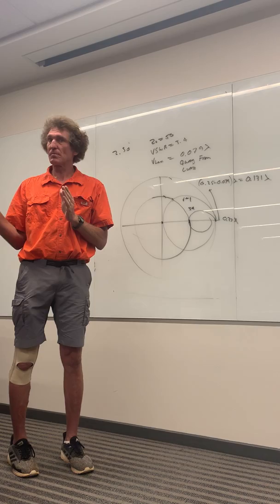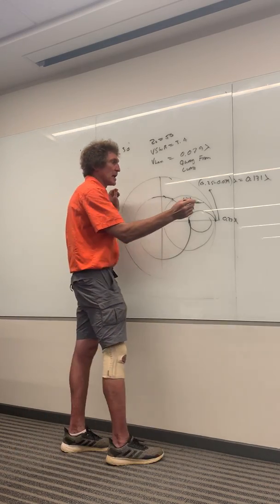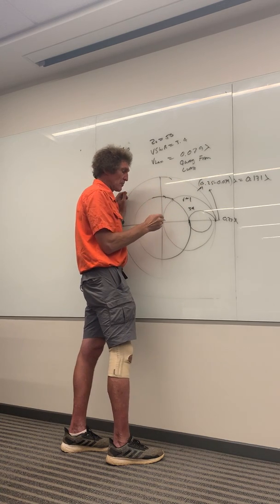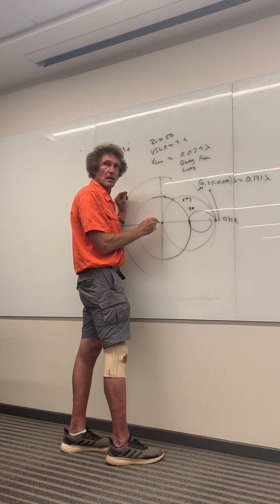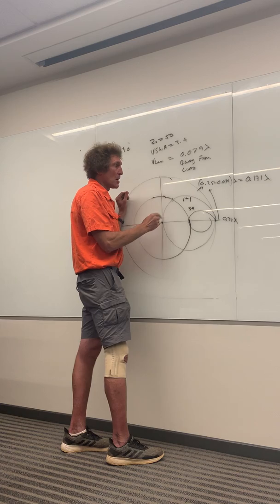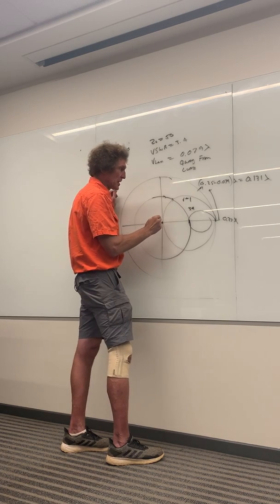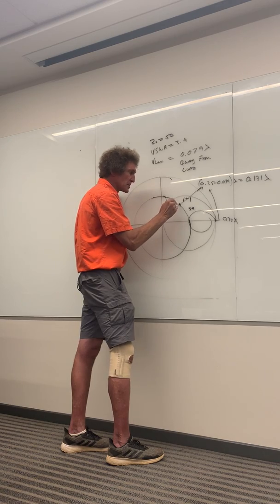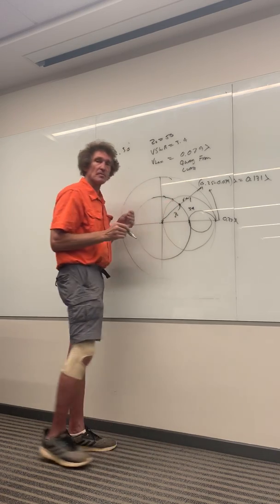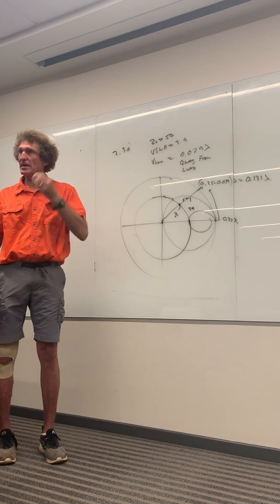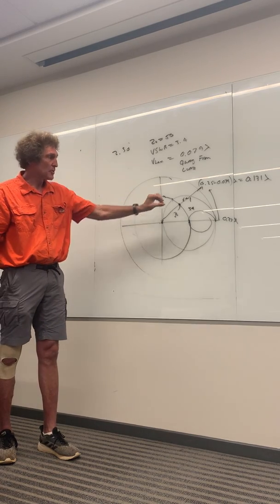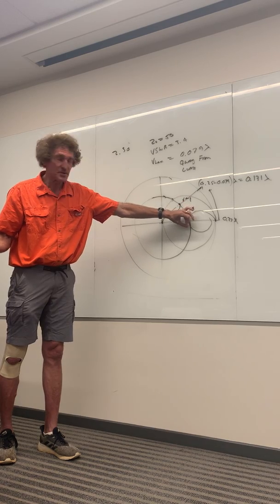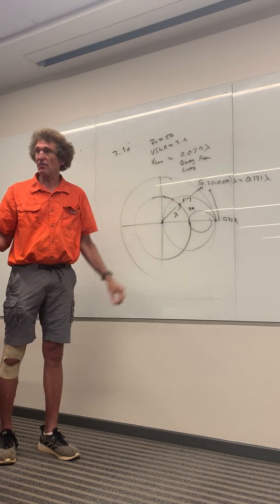Now this is wavelengths towards generator I'm using, all right? I'm using the outer scale on purpose. So if I take a look at that, it's about right there, right? Now what you do is draw a straight line through there, and this point is going to be ZL. That's the load, because if you think about it, if you normalized your load, it would be there, and then if you move 0.079 lambda, it would be Vmax. Do y'all follow me on that?